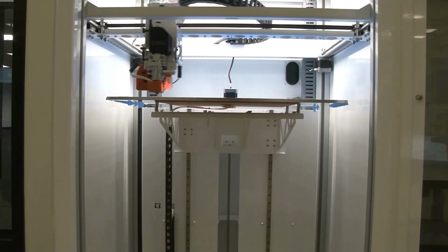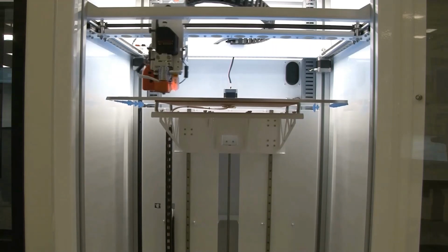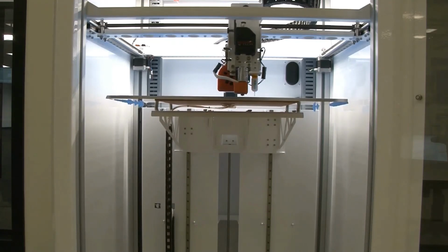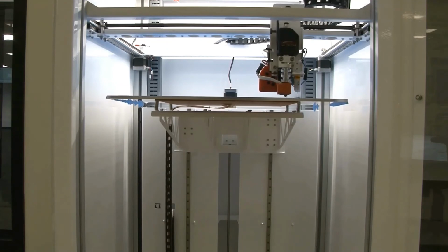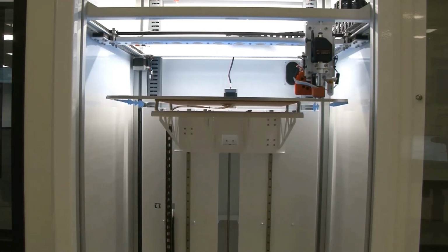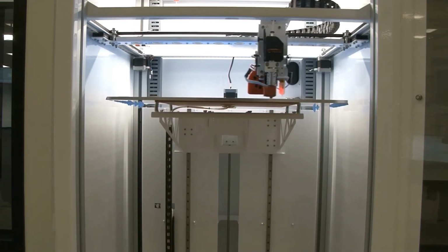Once all of the axes have been homed, the next thing that the printer will do is perform a 24-point bed probe to ensure that it can auto-compensate for any bed level issues that it may encounter. This will ensure that you have a high-quality print while compensating for any differences in bed height according to the heat map that is generated as a result of the 24-point bed probe. This is what's known as auto-leveling.